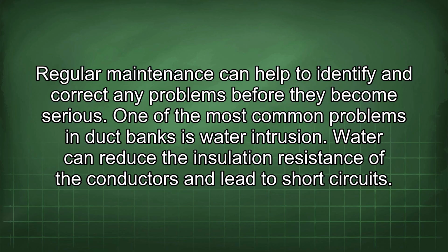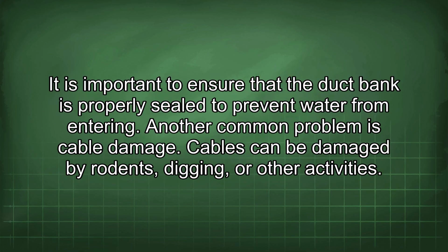One of the most common problems in duct banks is water intrusion. Water can reduce the insulation resistance of the conductors and lead to short circuits. It is important to ensure that the duct bank is properly sealed to prevent water from entering.